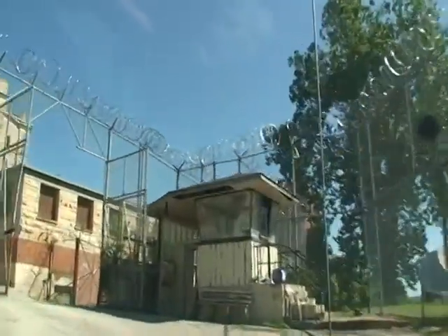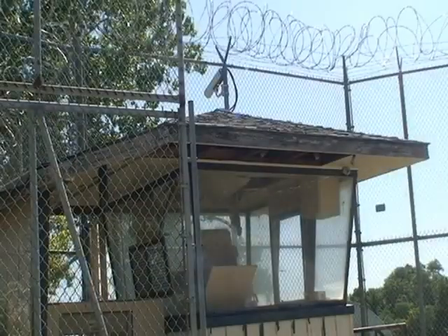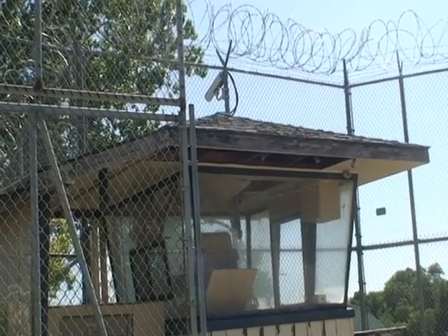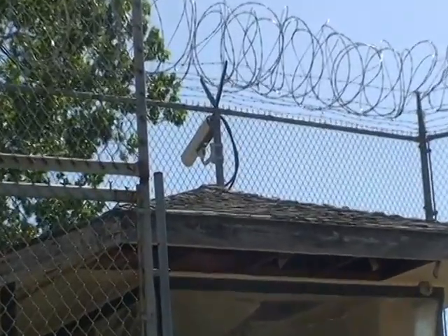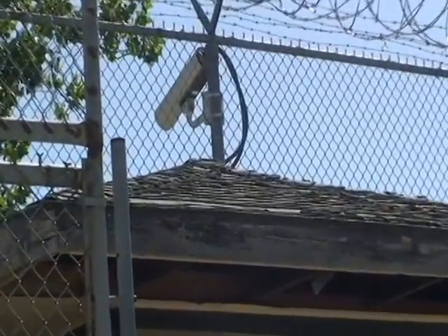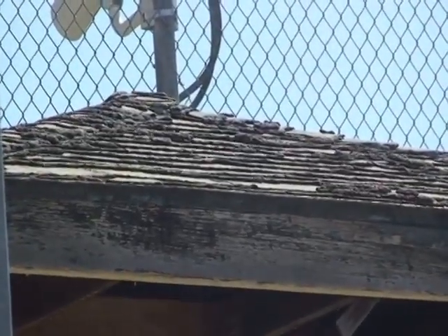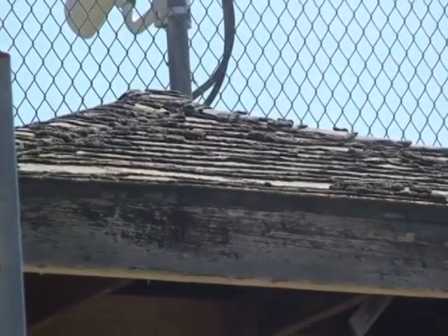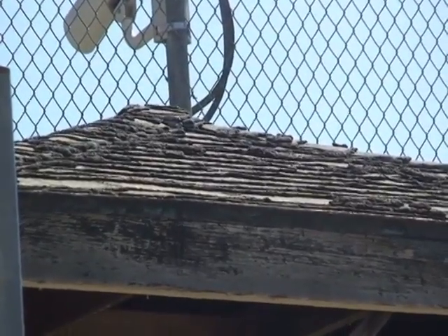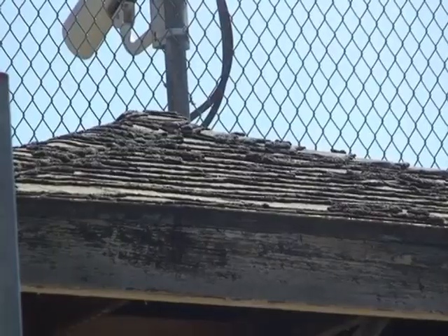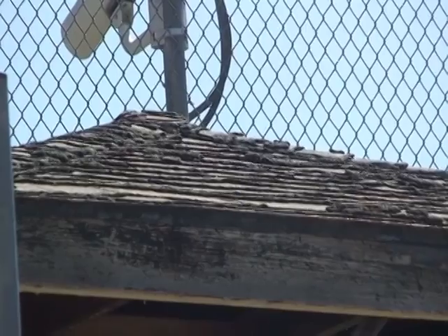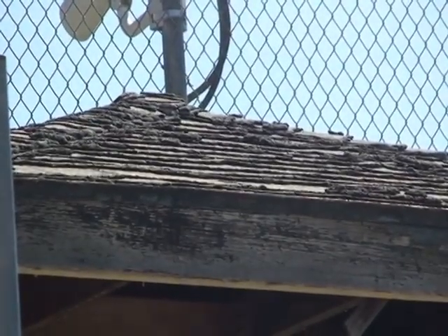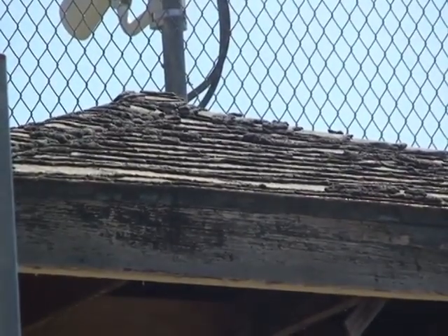Here's an example of some 3-tab shingles that are in bad condition. Normally roofing materials in good condition are considered non-regulated, non-friable material. In this particular case, these are weathered to the point that whoever does the initial inspection and pulls bulk samples, if they come back asbestos containing, would probably call this friable asbestos containing material. Keep in mind when you're looking at roofing projects, it's not at all uncommon to find multiple layers of roofing. While 3-tab shingles typically are not asbestos containing, you can find asbestos in both the felt underlayment as well as in the mastics for the flashings where the joints overlap.